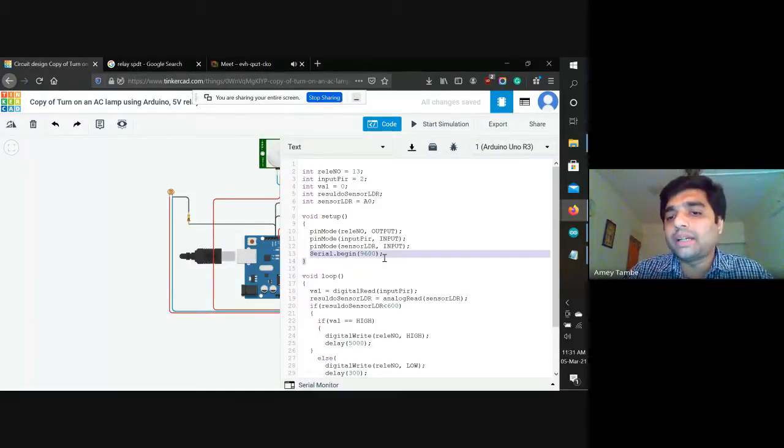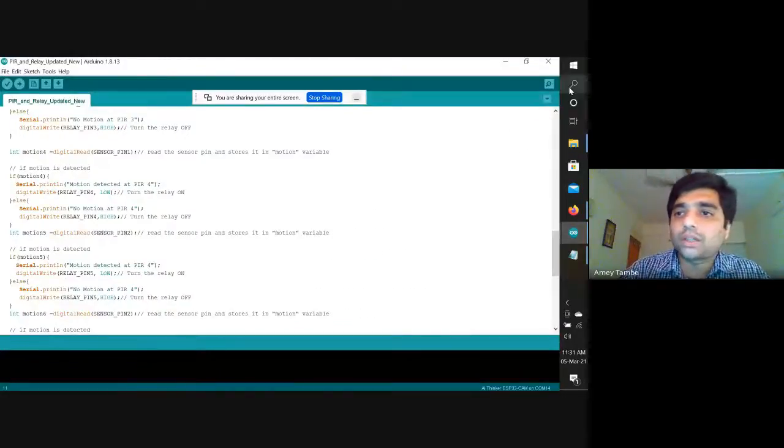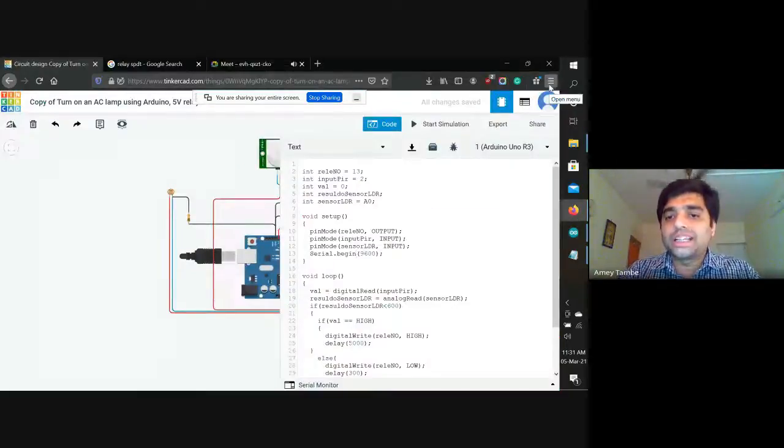Then I wanted to print something because I wanted to give a connection. So that is Serial.begin. Once I give the command Serial.begin, it will turn on my serial monitor. If I turn it on over here, it automatically turns on the display. The baud rate is 9600. I'll come to the baud rate when we take up the protocols; at that time we will understand it in a better way.